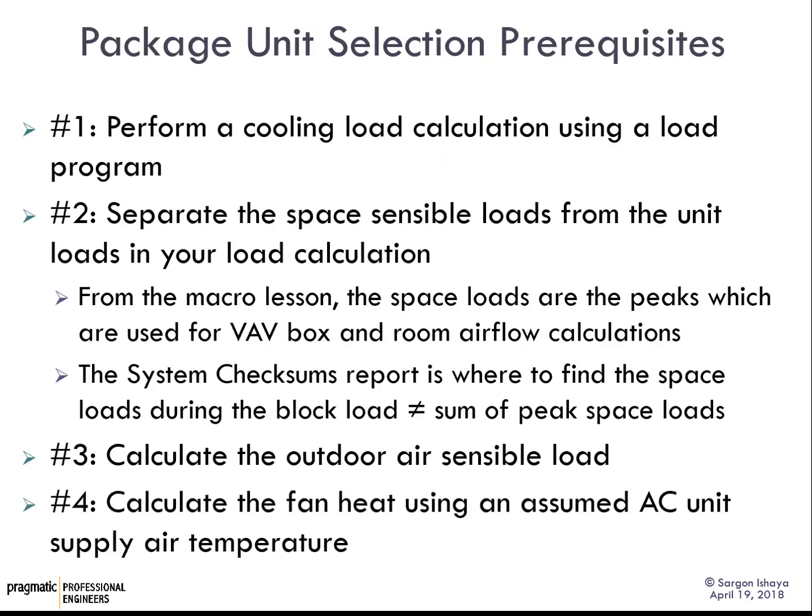Okay, so before you select a package unit, there's a certain amount of information that you need to get together. First of all, and I'm going to assume that this is already done for your project, you have to perform a cooling load calculation using a load calculation program. You have to separate the space sensible loads from the unit loads in your calculation. And in your projects, you should have already done this through the macro.